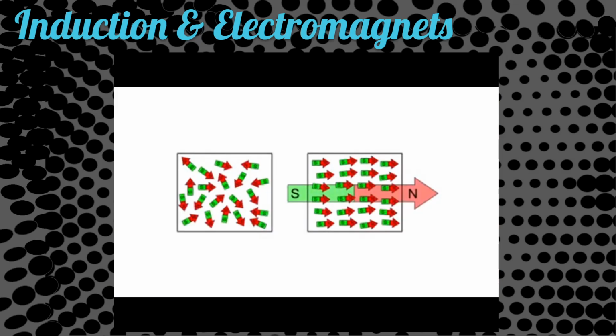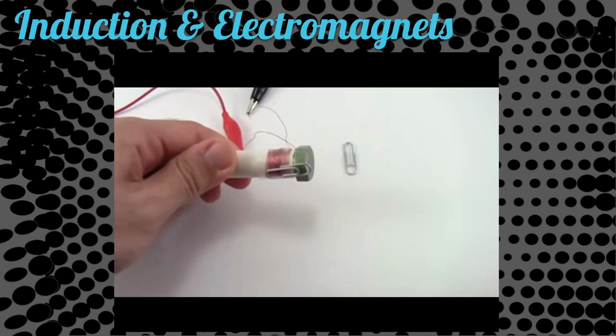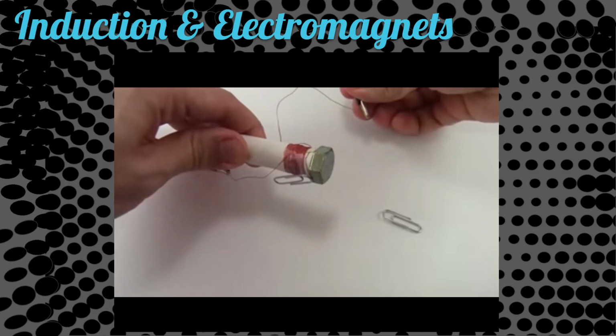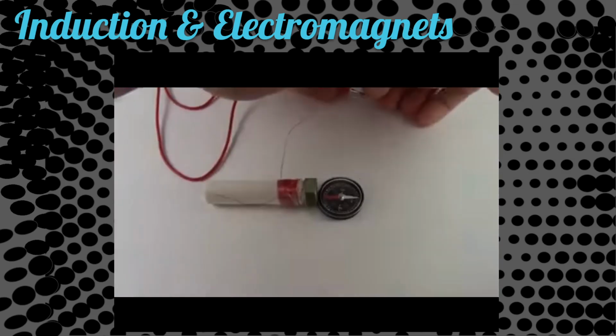Ferromagnetic materials have many smaller individual magnetic domains. Normally, these domains are aligned randomly and cancel each other out. However, in the presence of an external magnetic field, these domains align with each other and the external field, making the overall field much stronger. Watch what happens when I insert this iron bolt into the core of my electromagnet. Now it's finally strong enough to pick up a paperclip. Unlike a regular magnet, an electromagnet can be turned on and off by removing the flow of electrical current. If you reverse the direction of the electric current, you reverse the direction of the magnetic field.